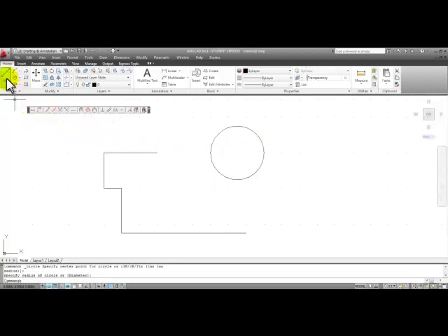Now we're going to draw a line, starting the line command at 11, 1.5. It's along the bottom line there that we drew. With our object snaps off, we can now use the grid to get to 11, 1.5 and left click. Then in the object snap toolbar we're going to pick snap to tangent and come close to this circle and left click. Right click and pick enter.